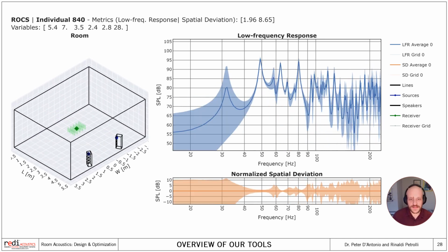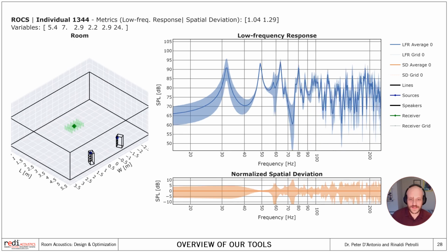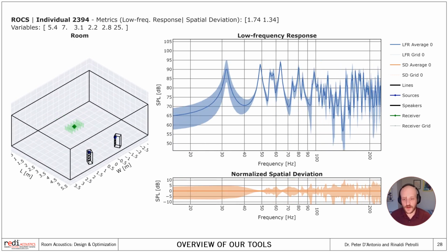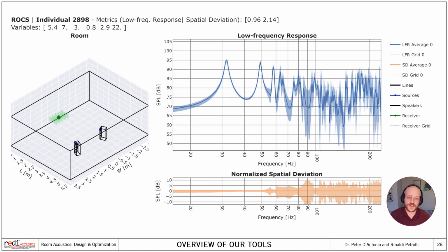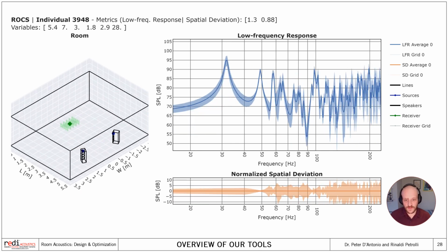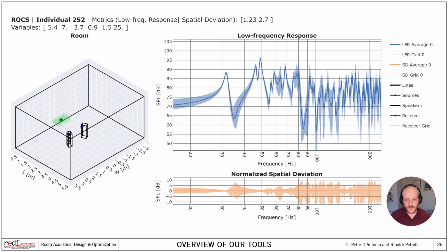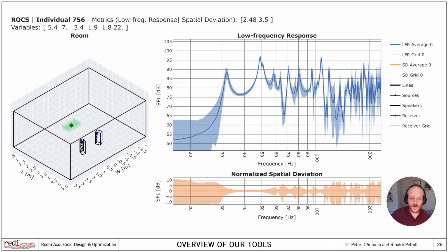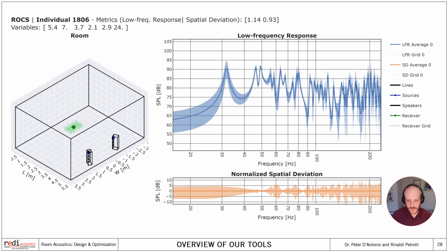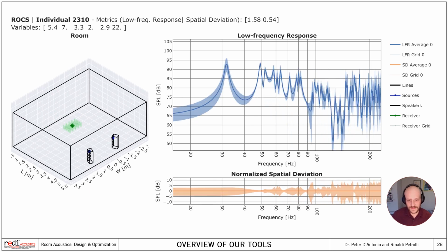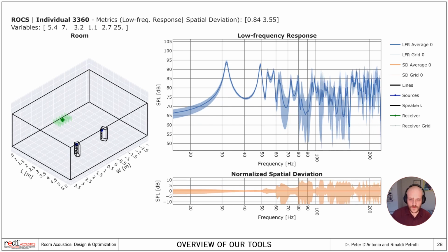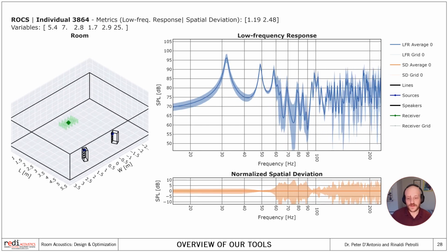The core idea remains the same as with NIRO. We are optimizing the room's design to achieve the best possible acoustical results at low frequencies, but since these are now cuboid rooms, we can be faster and more efficient by using some simulation shortcuts. In addition to this, since the rooms have a fixed number of surfaces, we don't need to account for reflections in the same way we do with more complex geometries. As we continue optimizing the room's basic structure in this first phase, we are setting the stage for the next steps. So once the room's geometry and positioning are finalized, we can move into treatment design and other advanced aspects of room acoustics.